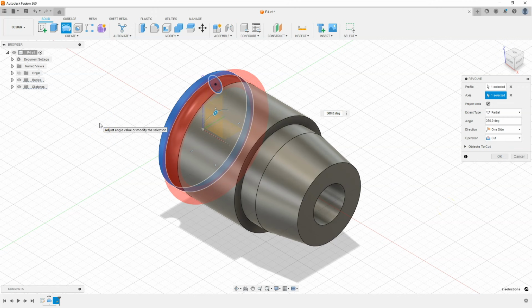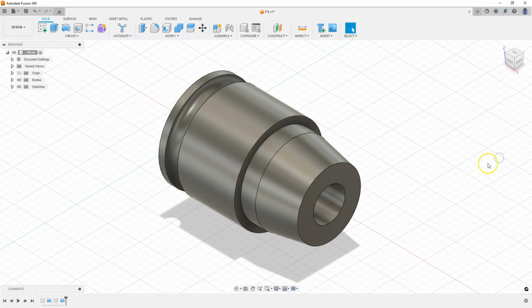And just as in the case of an extrude, we can create a 3D solid based on a 2D sketch, and based on the 2D sketch we can extrude a cut. So here we can create a 3D solid by rotating the 2D sketch around the indicated axis, and we can create a cut by rotating the 2D sketch around the indicated axis. Okay, these are the basic operations for creating 3D solids in 3D CAD systems.